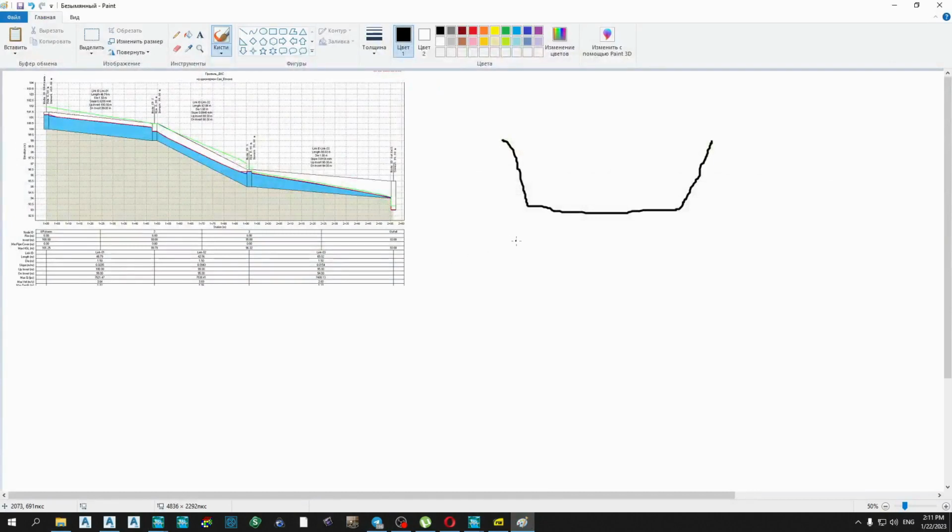The next step, I will recall what the energy of a cross section is. And the first attribute of cross-section energy is critical depth. What is critical depth? Critical depth is the theoretical depth which divides the flow into supercritical flow and subcritical flow.